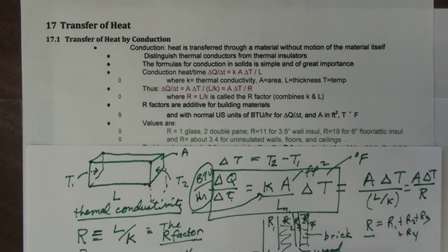That is, I've got my sheetrock, I don't have any insulation, this is empty. Then I put some wood, then I put some brick or some siding on. What's the R value of a wall, or a ceiling, or a floor? The answer is all three of them have an R value of about 3.4. So that's all you really need to know. Before the insulation, you have an R of 3.4. This is R empty.